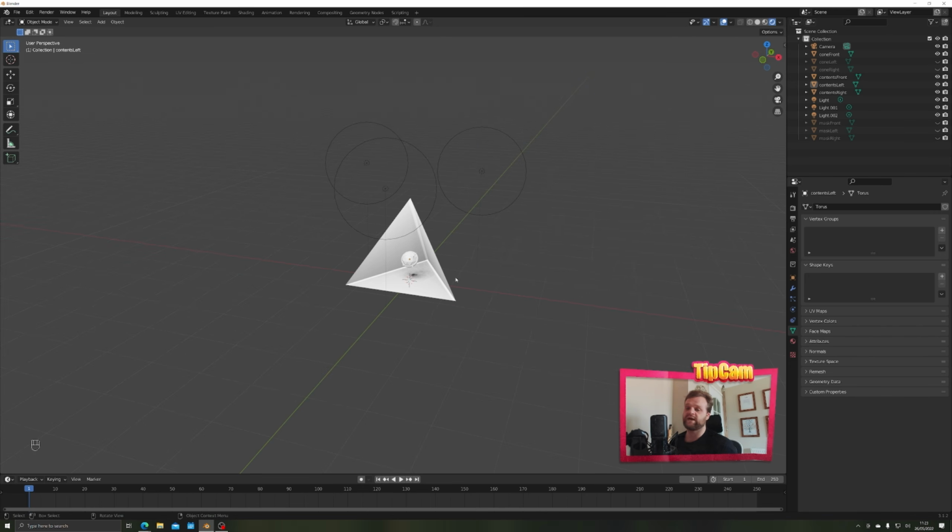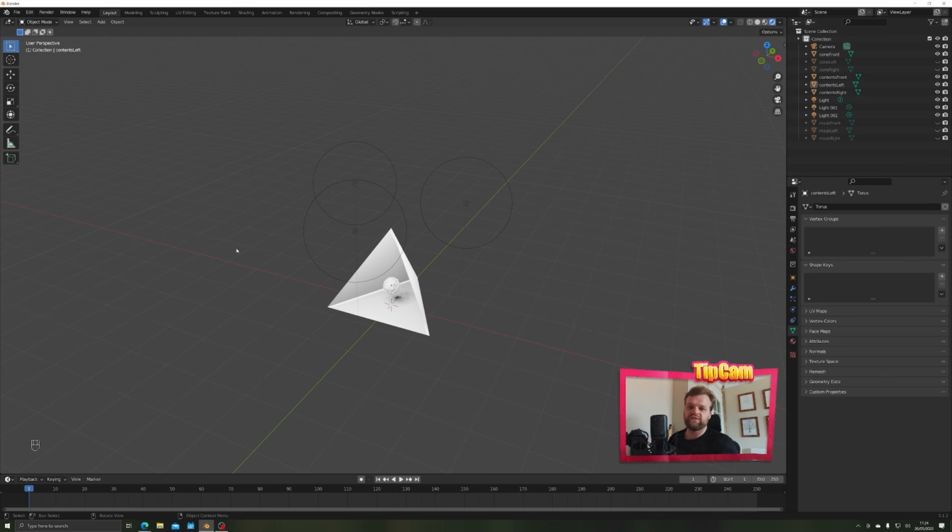The way we resolve that is using view layers. And view layers work by hiding or showing collections of content when you do a render. If that doesn't make sense, don't worry, it will by the time we've popped everything into a collection. So let's get started moving it into the collections, and then we'll go through what the view layers mean.